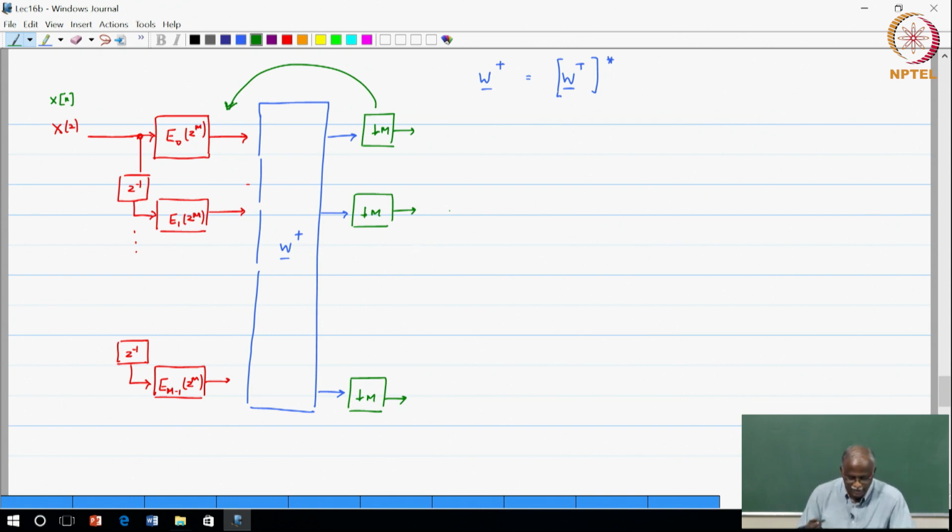So, basically what we can write down here is that this turns out to be a very efficient implementation. We have utilized several of the tools that we have developed: the interconnection of multirate blocks, the noble identities, and of course the shifting of the filters, and what happens when you have the DFT coefficient raised to the power m.